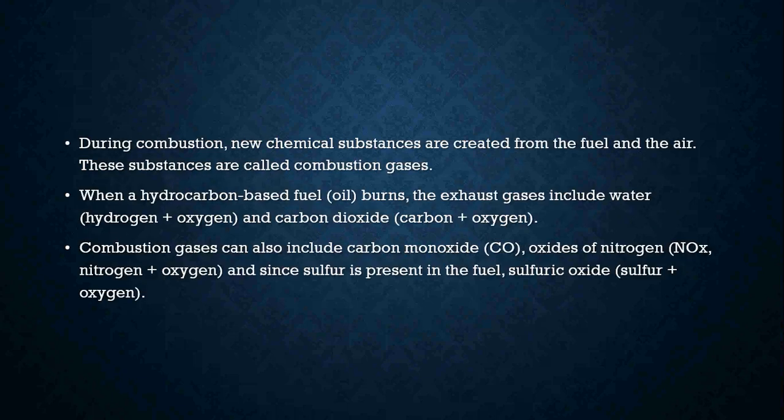Where we get into this is we have to understand how our fuel and our air react with each other. During the combustion process, new chemical substances are created from the fuel and the air. These substances, again, are called combustion gases. When we have a hydrocarbon-based fuel, such as oil, and it burns, the exhaust gases are going to include water and carbon dioxide.